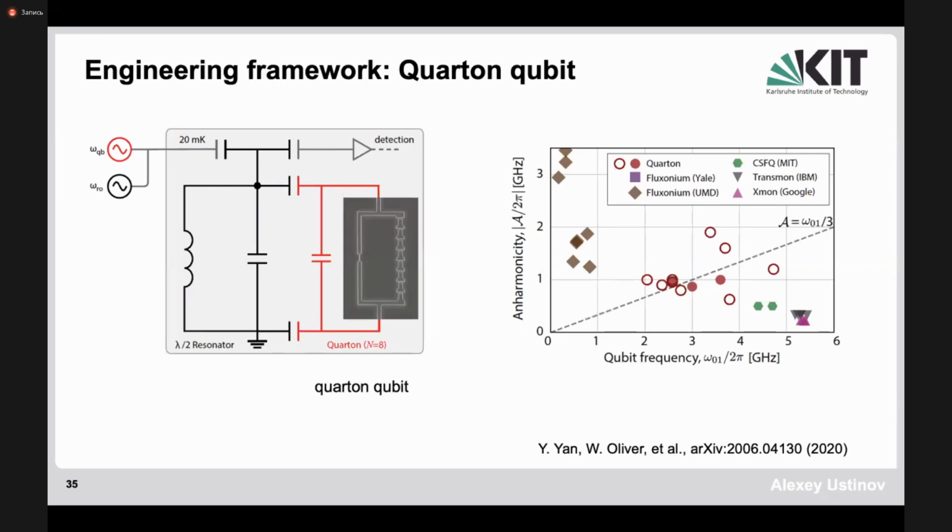complementary pair of transistors. If you have an NPN transistor and a PNP transistor, then you can make a device very symmetric, and combining those two actually makes the amplifier much more linear and much more practically useful than an amplifier made of transistors of a particular polarity. Now, here you combine two devices of opposite harmonicity, transmon and this quarton qubit, and this also makes the schematics much more convenient.